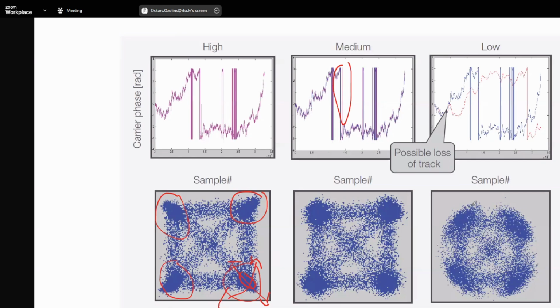And if you have very high phase noise, then your compensation gives you something like these banana shapes. I'm very bad at drawing bananas, but right. Which means that your algorithm is not good enough to compensate for the phase noise there is. So either you use a more complex algorithm to compensate for the phase noise, or if you cannot find a more complex algorithm, then you need to find a better laser, just to reduce the phase noise in the system.